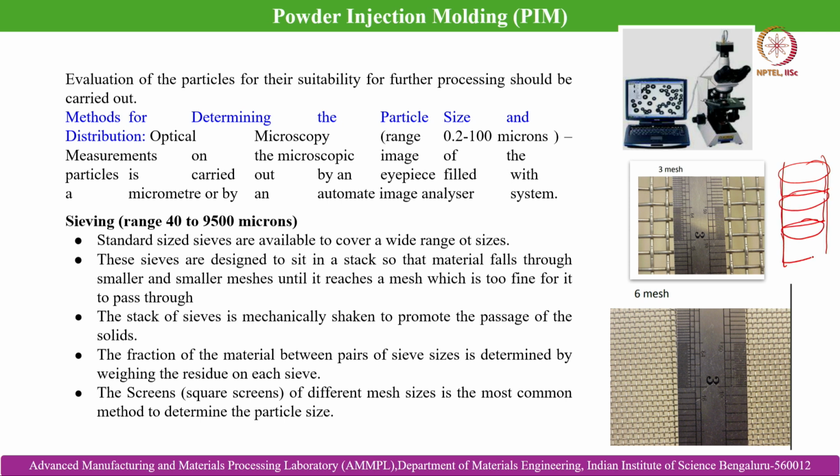For example, multiple sieves are stacked, and the powder particle size ranges vary based on the mesh size, which becomes finer and finer as the powder particles drop to the next sieve at the bottom. Thereby bigger particles are trapped at the top and the smaller particles pass through.